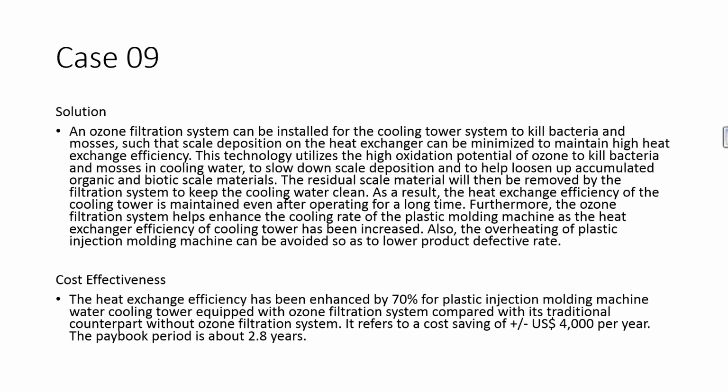The problem is traditionally the barrel tubes of plastic injection machine are heated up by the resistance heater coils around the barrel tube by conduction. A large amount of heat is lost from the surface of the tube to the ambient air, which also increases the ambient temperature of the workshop.